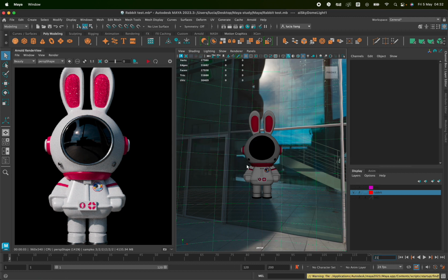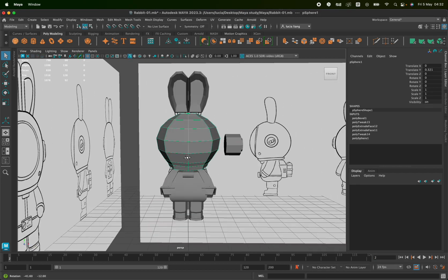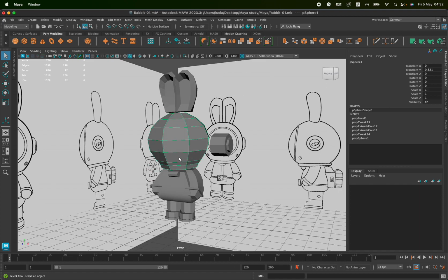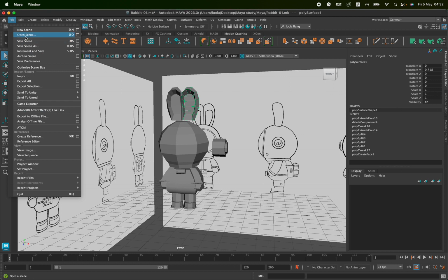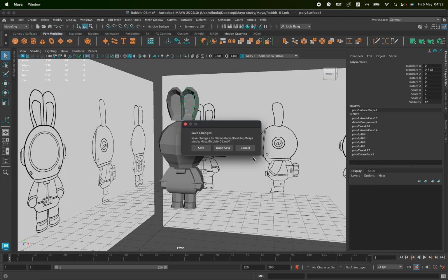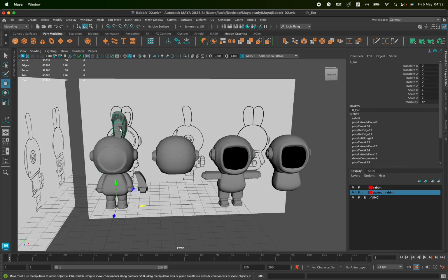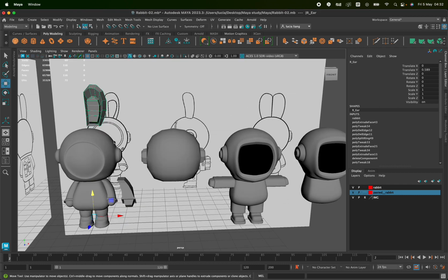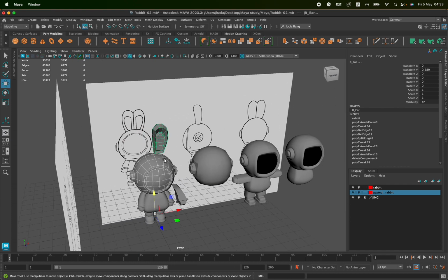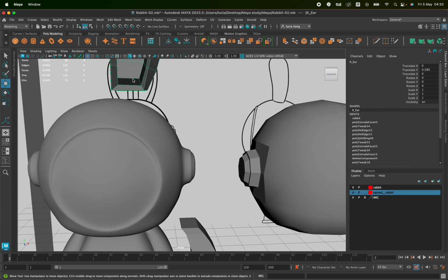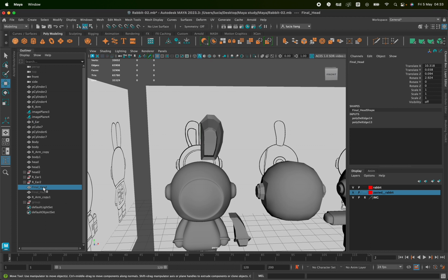At the beginning of the modeling, I used a polygon sphere, but the normal is not good, such as when you need to dig a hole, it is difficult to operate. Then I tried a lot of methods and found that the best way to make a character is to use a cube with a smooth command. And then the overall modeling process of this rabbit is a little complex. The first important decision was that I connected the ears and head together and needed to use the bridge command. The advantage of this is that it will look more realistic.